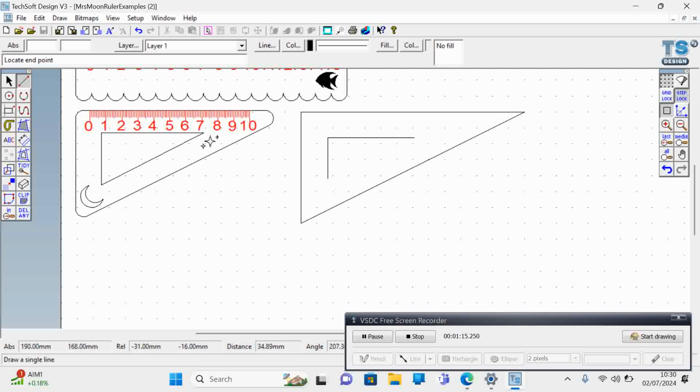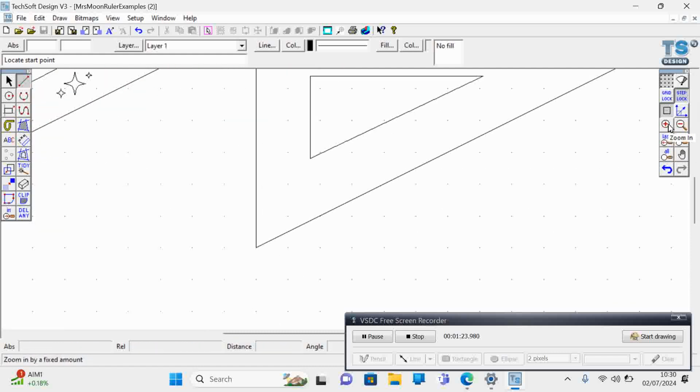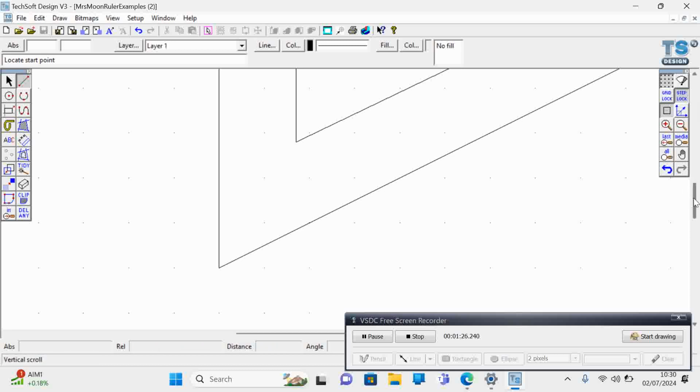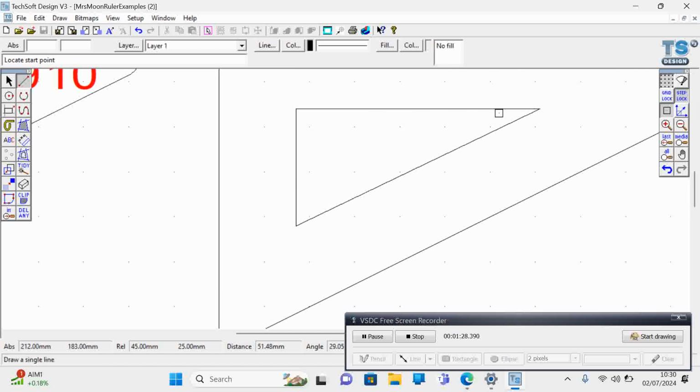And then from there, I'm going to draw my next one using the attach tool, and it will find the nearest edge and attach to it. So if I zoom in, there should be no gaps, because it won't cut out properly if there are any gaps. Fantastic, it has attached. So you won't need your attach tool again, so you can click off that one.